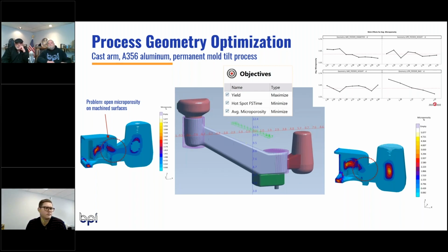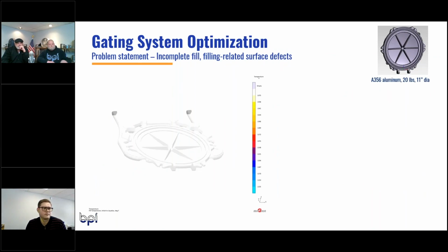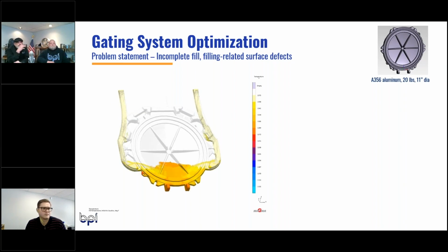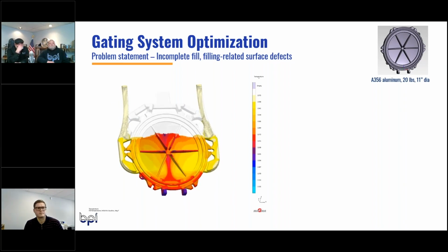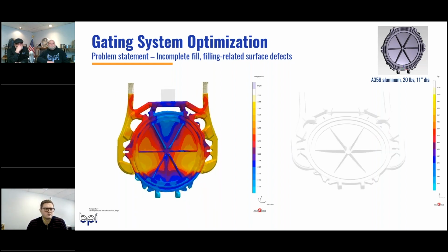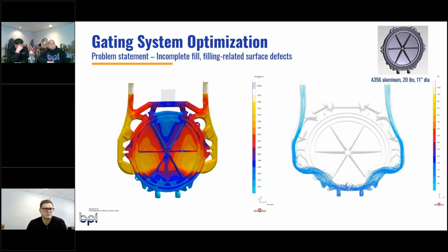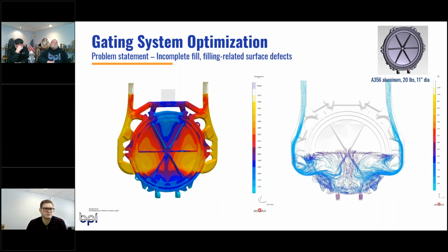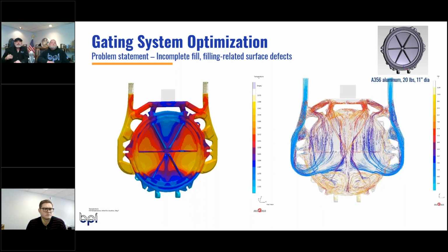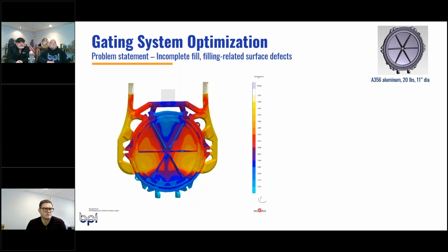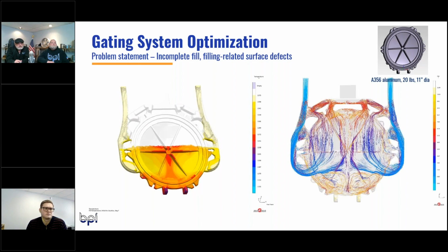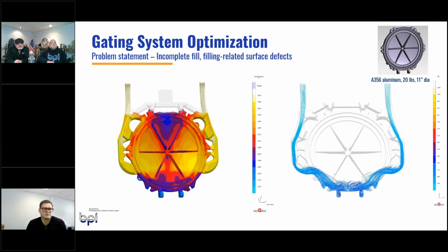Great, thank you. All right, let's move on to the next step. I think this is going to be a little bit more exciting because we're looking at a fluid flow problem. We're filling the mold with liquid aluminum, and again, I wanted to emphasize that the term here is casting process simulation. It's not just solidification modeling, or mold flow or flow modeling, as has been thrown around in the industry in different ways. It's trying to capture the entire metal casting process from bringing the metal into the mold, allowing it to solidify, and then allowing it to cool to room temperature.